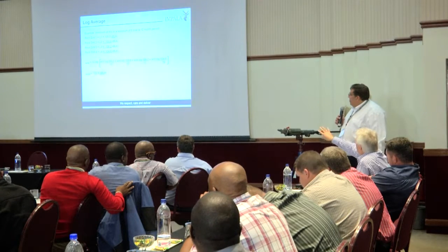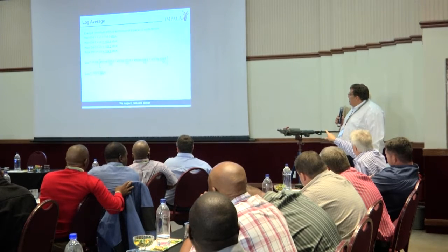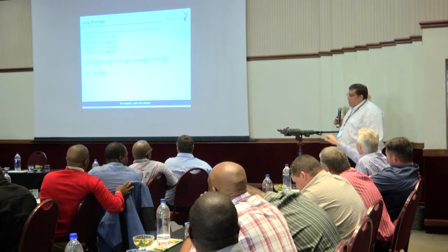Any questions? If you just do the formula the way it is, you're not getting 105.8. What I picked up is in the brackets, once you've done that, there are 4 machines, you divide that first by 4, and then you take the log, multiplied by 10, to get the 105.8. Okay, maybe with the copy and paste, I just skipped that step. I couldn't figure it out at first.